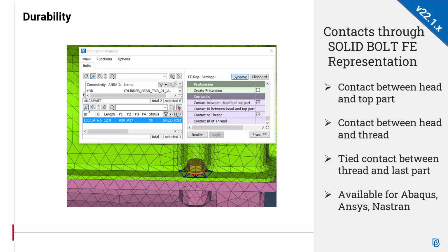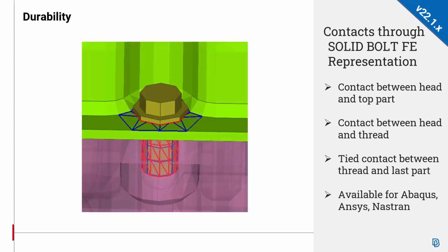Moreover, contacts through the solid bolt connection can now be automatically created between head and top part, between head and thread, and tight contact between thread and last part. This enhancement is available for Abaqus, ANSYS, and Nastran.